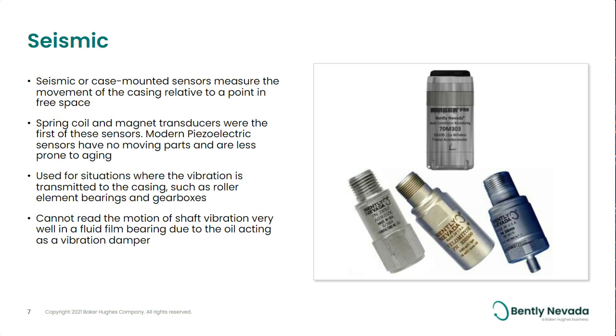And this was important because if you had an accelerometer and it had a fairly long cable run, when you integrate, the low frequency components get amplified significantly.